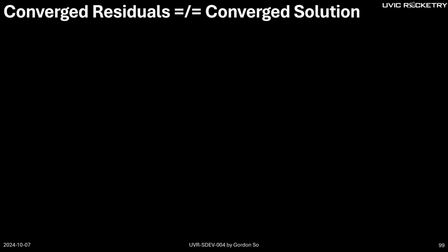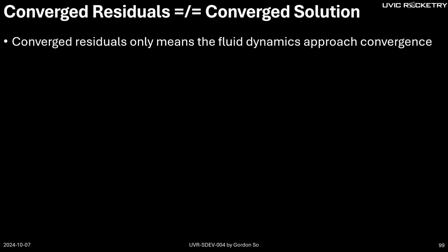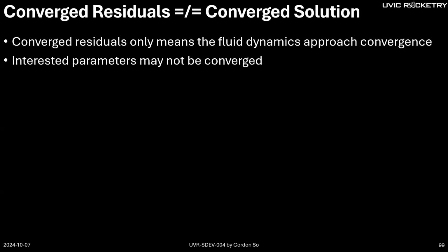Another thing is converged residues doesn't mean a converged solution. This is a distinct difference, because it only means the fluid dynamics model converged, but that doesn't mean the thing that you want converged. So you also need to monitor your design parameters.